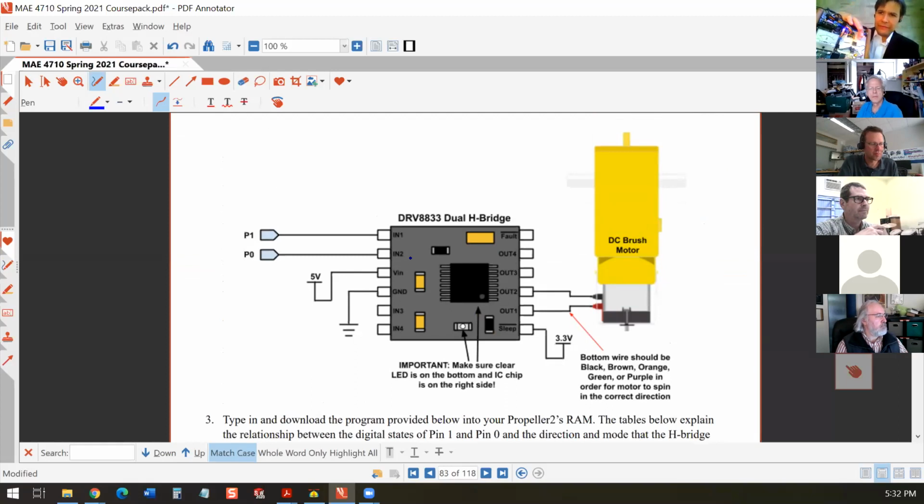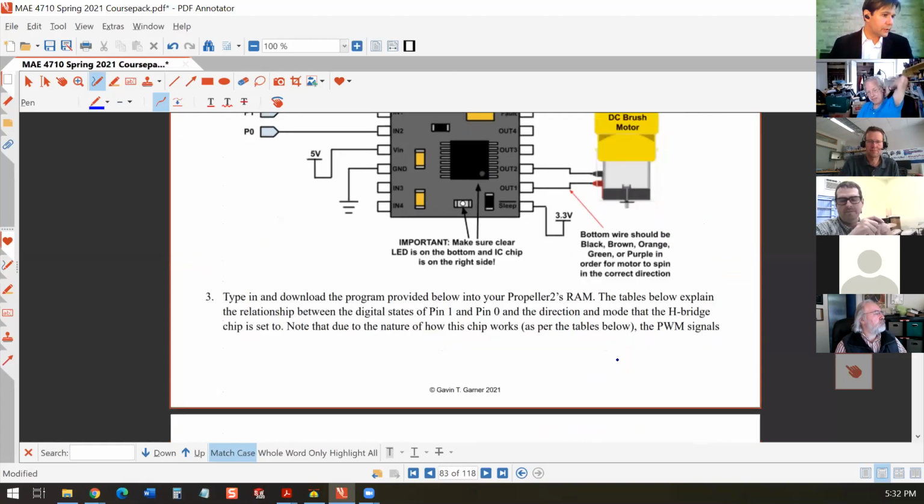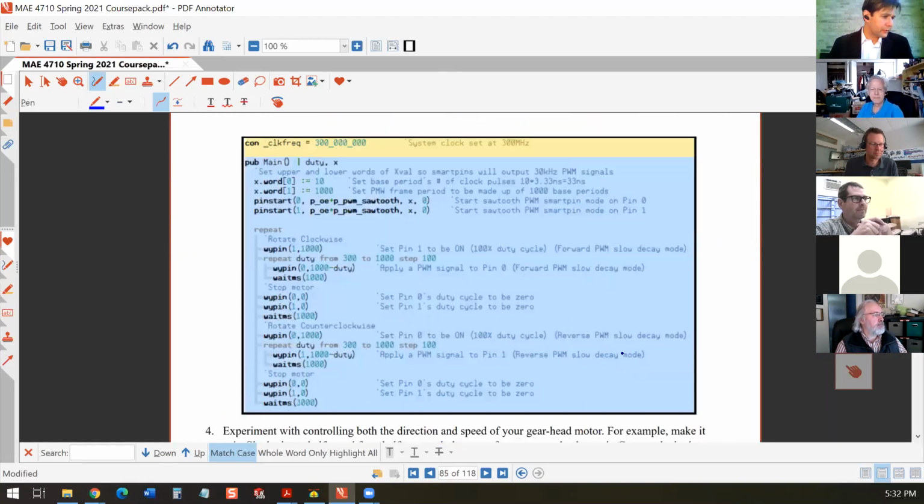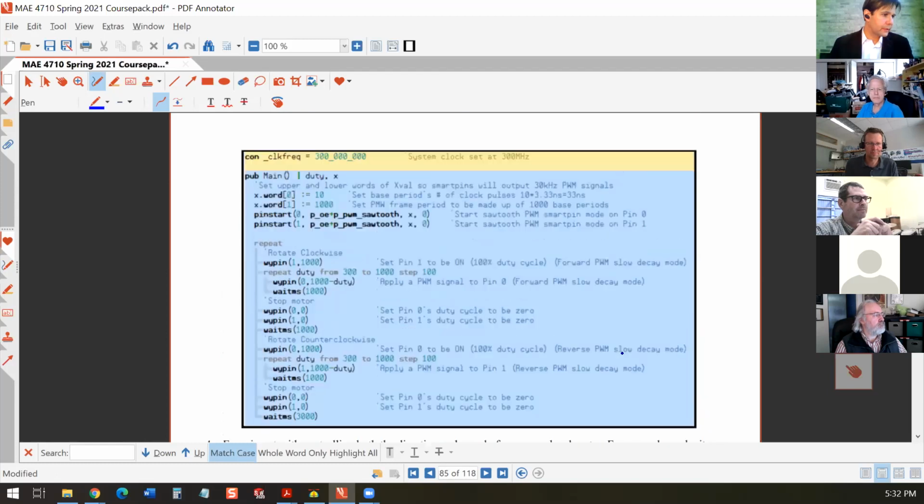There's a lot of variation in the various vendors that had these, so some of them have different colored PCBs and stuff, but they all seem to work okay. So it's nice. It's a dual H bridge, originally designed for bipolar stepper motor control, but it's nice for robots with 2 brushed motors as their wheels. And it also just ran off of 5 volts, which was nice.